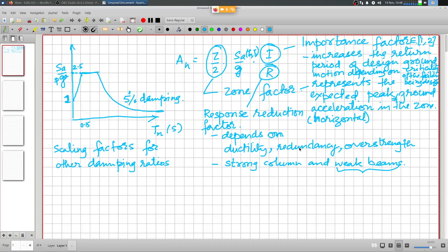And then the ductility. As I said, ductile behavior is of course very, very essential to absorb the energy that earthquake input ground motion feeds into the structure, and there is only so much that you can store by virtue of elastic strain energy.